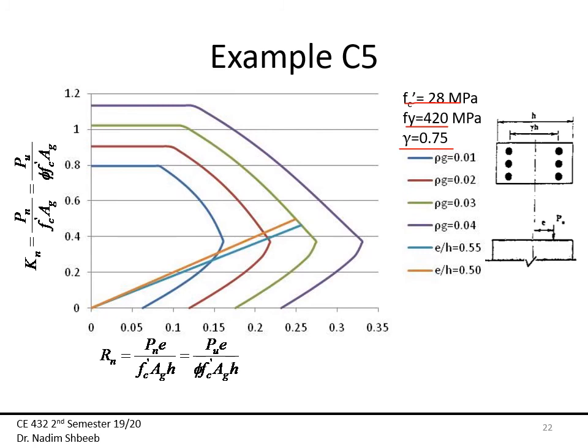And I also have a MATLAB program that can actually do the interaction diagrams for me as well. But again, I was lucky enough to get gamma 0.75. Sometimes if you don't find the gamma, let me re-emphasize that, then you have to use the gammas surrounding the value that you want. So in this case, for the 0.75, you need a gamma at 0.7, do all that work, and then you need another gamma at 0.8 and do that work as well.